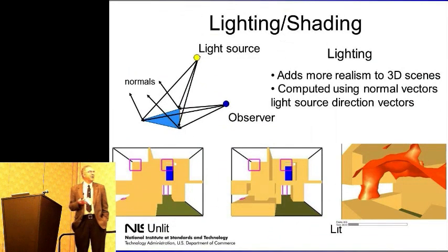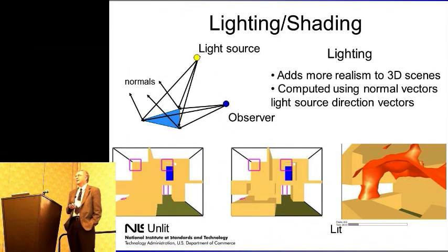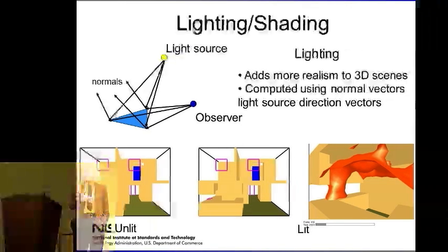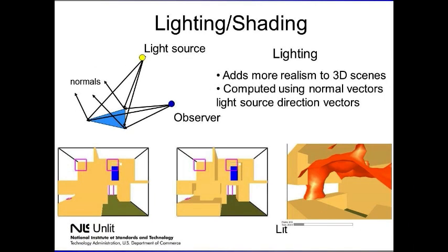Now, basically I'm going to be talking about lighting calculations. OpenGL, which is the software tool that I use to present the data, does a lighting calculation in the background, so that when you're looking at the blockages, I have to tell it the direction that the blockages are pointing, and I create a virtual light source within Smokeview that's there solely to give the geometry more of a three-dimensional sense.